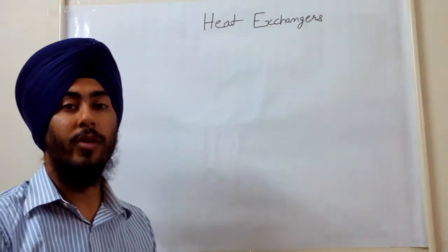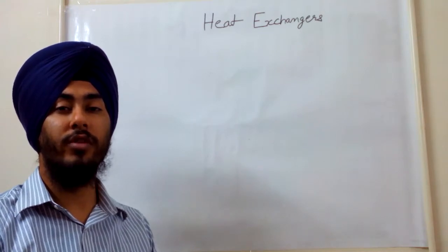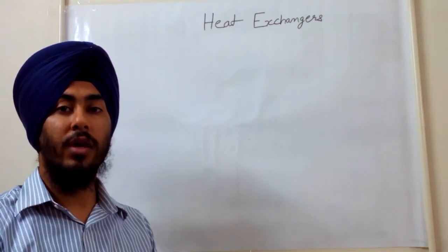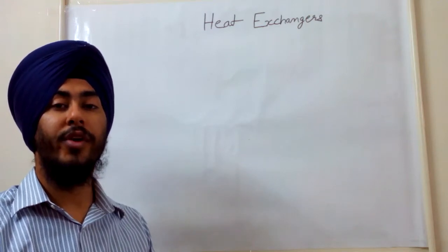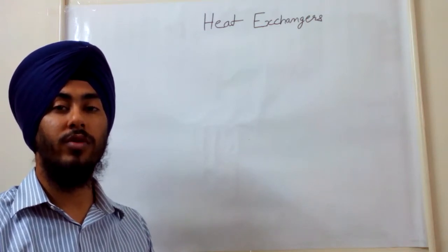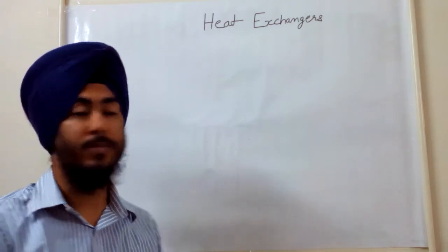There is an important point. Please note it that whenever all the four temperatures are same, in case of a parallel flow or counter flow heat exchanger, the LMTD of counter flow will always be greater than the LMTD of parallel flow. Please note it.